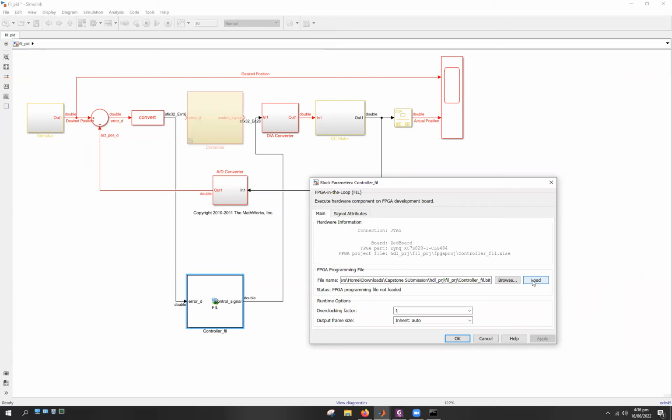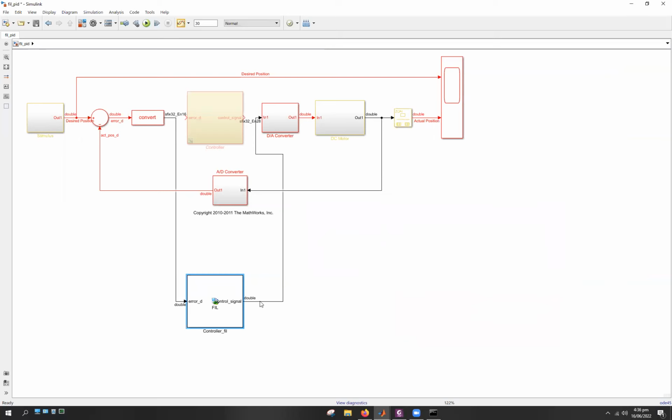And when you do load it, the FPGA would give you some signal in the form of an LED. For example, the Zed board turns on this blue LED when a file starts loading onto it. So you have to perform this loading task, and then you will have to press OK. Since I don't have the FPGA at the moment, I would just simply tell you the steps that you have to follow.